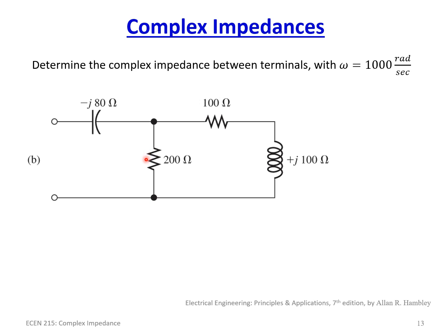So in that case, you're going to do the parallel resistance equation, which is 200 times 100 plus j100 divided by 200 plus 100 plus j100 ohms. We could rewrite the numerator as 200 times, in this case it's 100 and 100, so we take the magnitude of that: 100 squared plus 100 squared, take the square root, that's 141.42 ohms with a phase angle of arctangent of 100 over 100, that's 45 degrees.